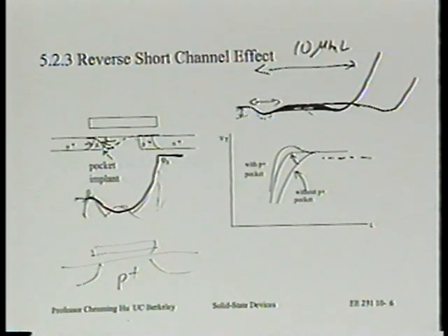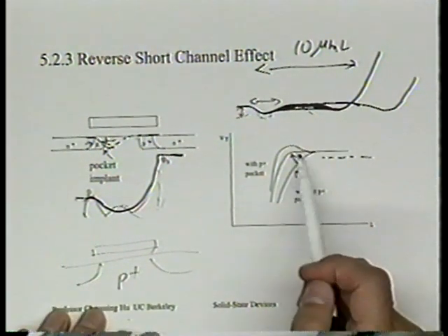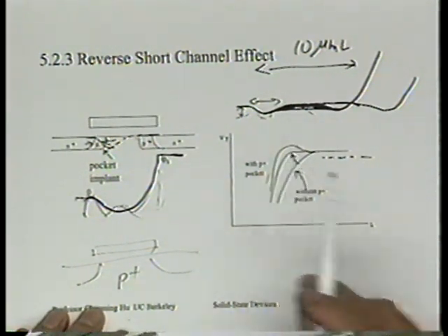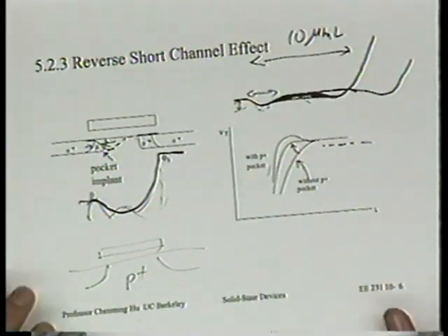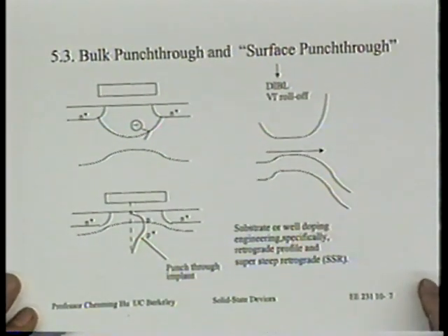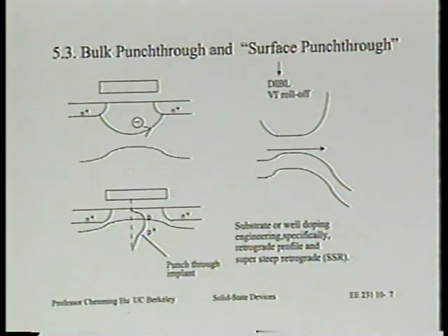All right. Okay. And of course, this is the beginning really of the question of how to optimize this reverse short channel effect, because the goal really is not to peak too much and to delay this roll off as much as possible, right? So if you are interested in this topic, you have the tool to answer those questions, but we will not go into the details, all right? Okay. Any other questions about reverse channel effect? All right. If not, let's look at the new topic.